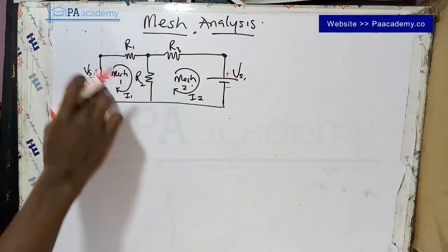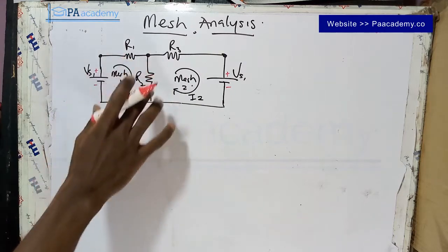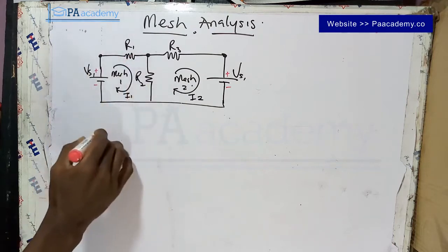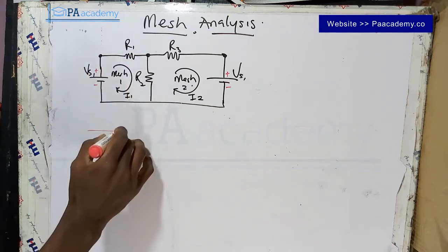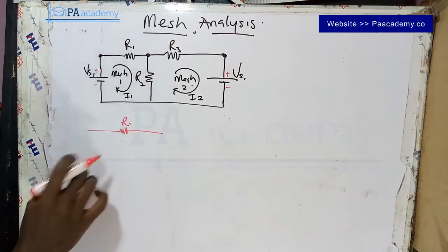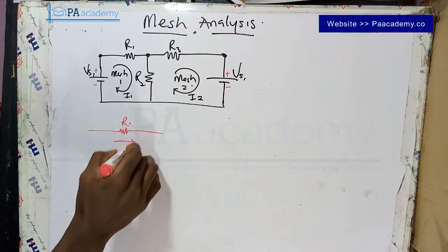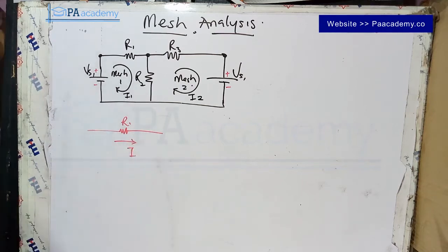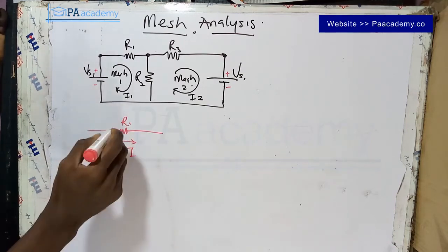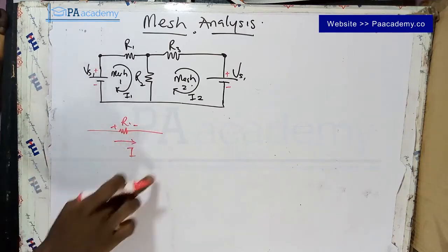Alright, so in a clockwise direction, remember that, let me also say it here, when you are dealing with Kirchhoff voltage law, if you are moving in clockwise direction across a particular element, let's say like this. So let's take this to be our R1, for example. Let's bring this out. If this is our R1, if our current direction is like this, that's the direction of our current. So that means the polarity that we are going to be having for this resistor is going to be plus to minus. That's because it is going in this direction.